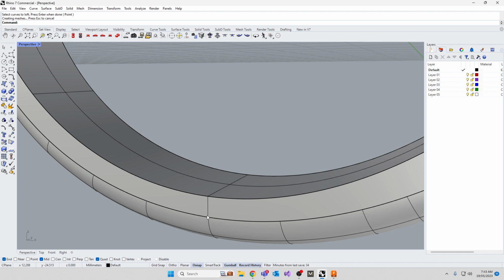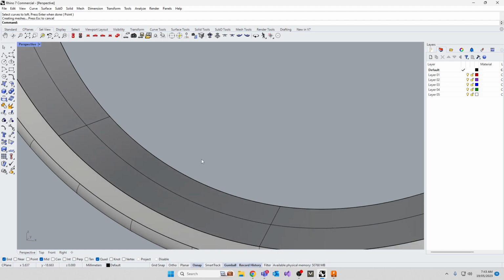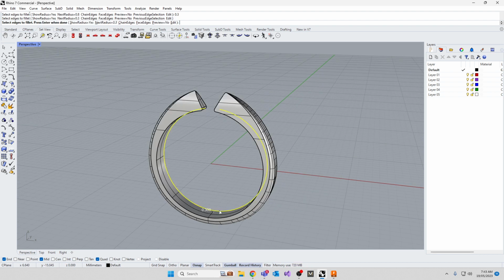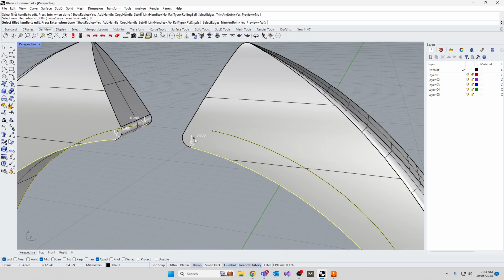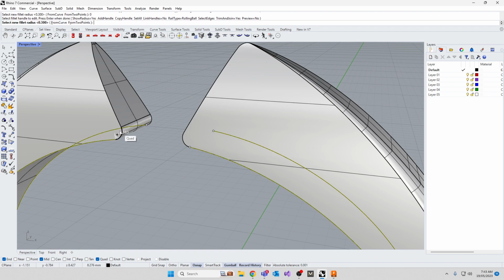We're going to do a fillet. This time we can't go as far because you can see that it's 0.8. If I do a fillet here, I'm going to go into the other fillet, which is also a weak point of Rhino. So we're going to do another fillet edge. Okay, I think that this is going to be about 0.3 this time. So I'm going to grab that edge and this edge, and same deal. At the top here, we're going to go 0, 0, 0.